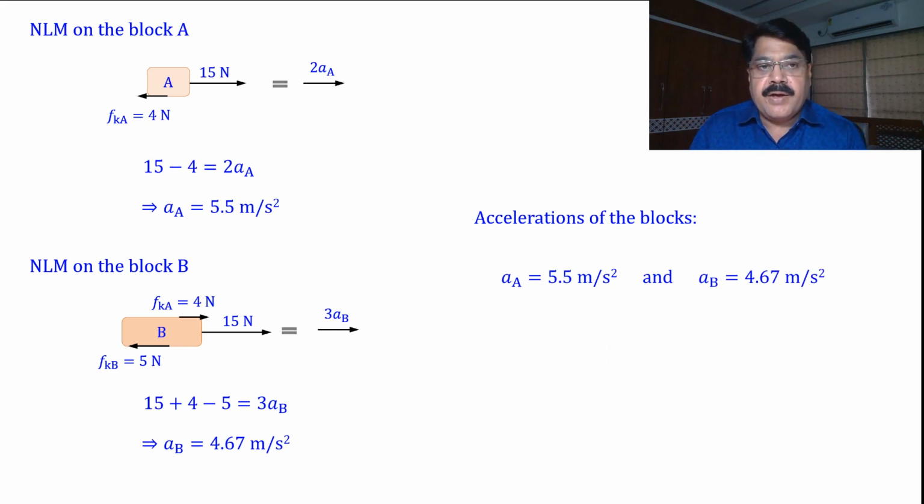Now, till so far, for whatever complexity a problem has, we have seen all the critical decision points and what they are. I am again suggesting deciding the direction of friction. If it is apparent, then write it. If it is not apparent, try to find accelerations assuming friction 0 at the surfaces in contact under investigation, and then calculate the relative acceleration, and that relative acceleration will suggest to us the sense of sliding and the sliding tendency. So the direction of friction, in that way we can decide.